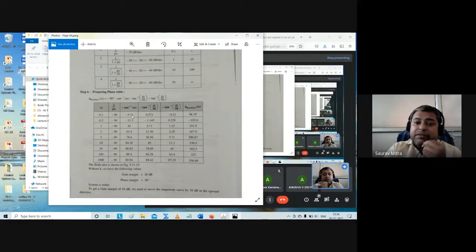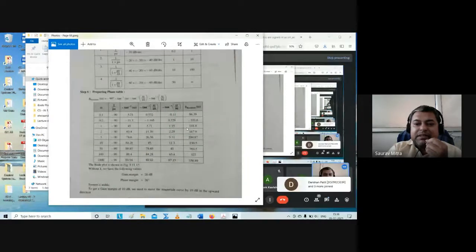Okay, so one very interesting thing you can find here is at 0.1, the phase is positive. Okay, and it is starting from positive. And then at 0.2, the phase is coming to be negative, minus 102. And I'm sorry to tell, here is a mistake actually. All these below phases should be negative. Though they have written all the phases as positive, all these phases actually have to be negative. So I'm sorry, this kind of printing mistakes are there. All these phases below also you'll be finding they're all negative, and they will be getting added with minus 90. So everything below is minus 90.